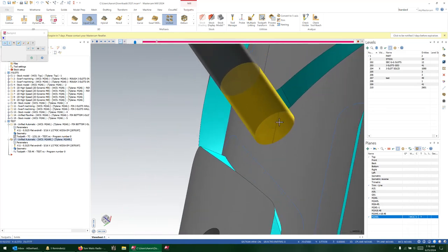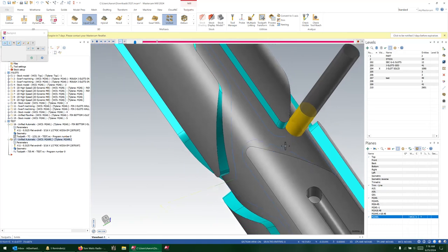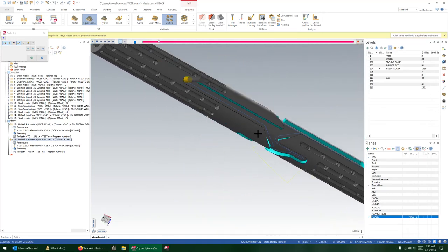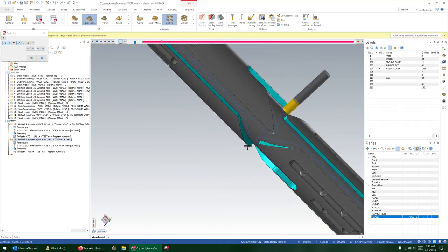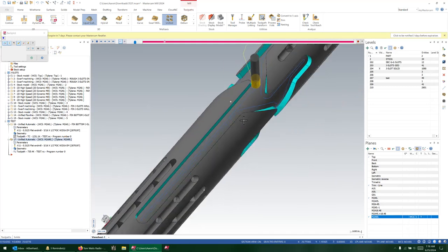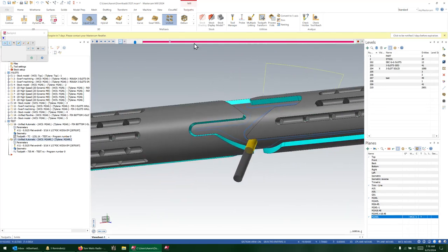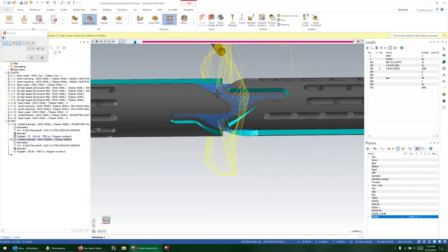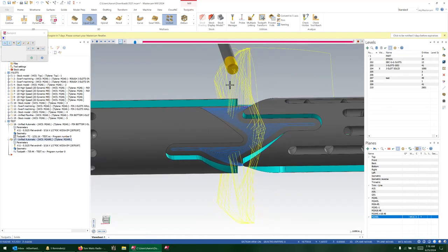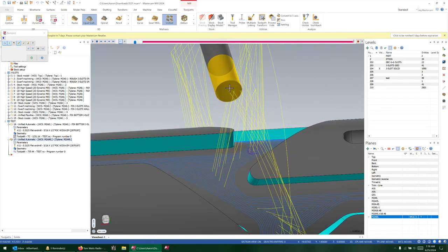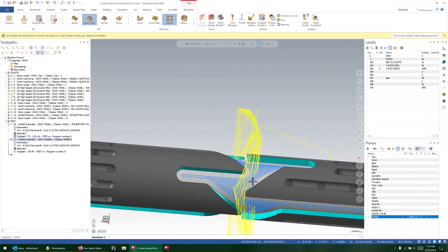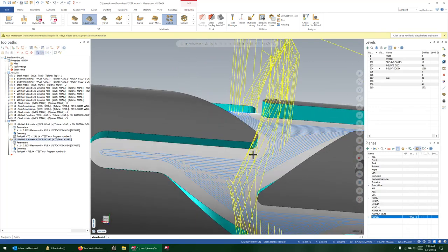Now, obviously, you need to make sure that you've got a center cutting end mill to do this. But again, I would highly, highly, highly recommend that you do not use a flat end mill to do this shape. You're not going to be happy with the results. It's not going to look great. You'd be much better off doing a ball mill or a heavily bull-nosed end mill to cut that so you get some nice scallop there.